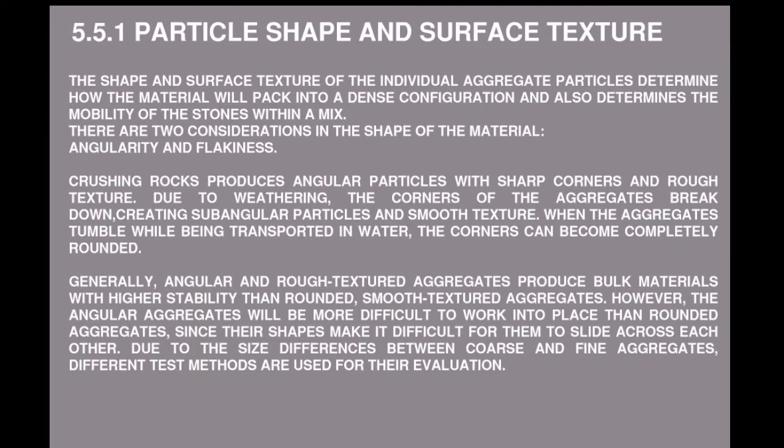Crushing rock produces angular particles with sharp corners and rough texture. Due to weathering, the corners of the aggregates break down, creating subangular particles and smooth texture. When the aggregates tumble while being transported in water, the corners can become completely rounded.